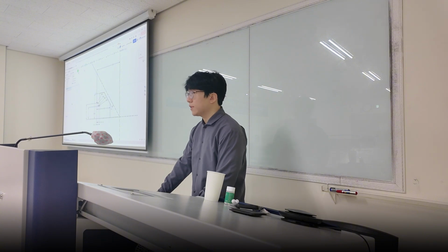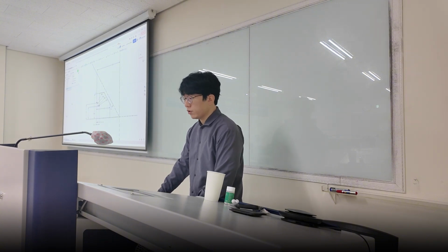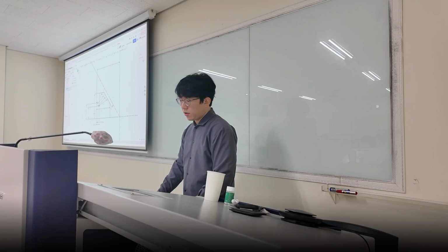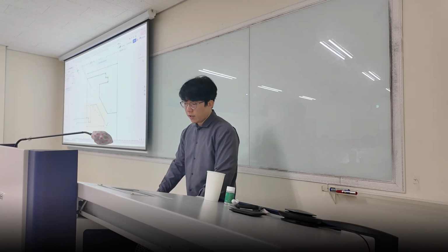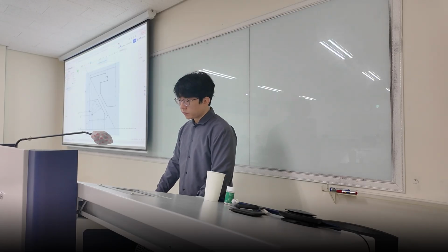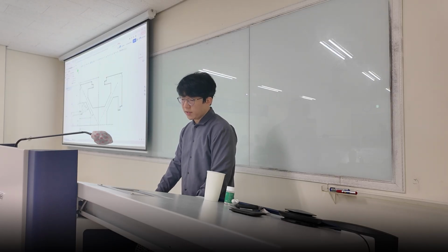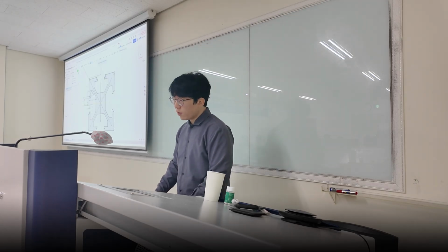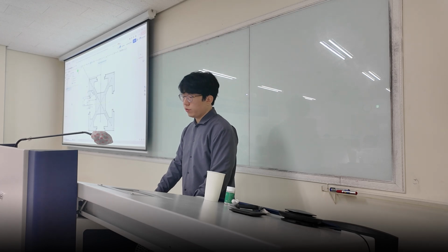This is sketch fillet. This is not the bulk fillet that we used. You can see the radius is 0.2. And then we're going to mirror this, and we're going to have another fillet at the end. Then we're going to mirror this again. So you see, we draw this basic sketch here, and then mirror once to this oblique line, and then we mirror the entire thing to the y-axis. And then we're going to mirror this again. So it's really important to draw the first thing properly.